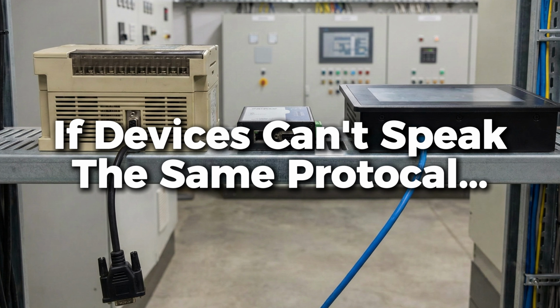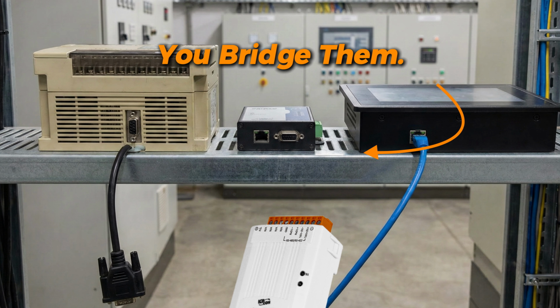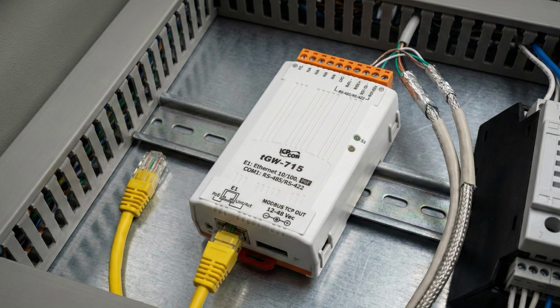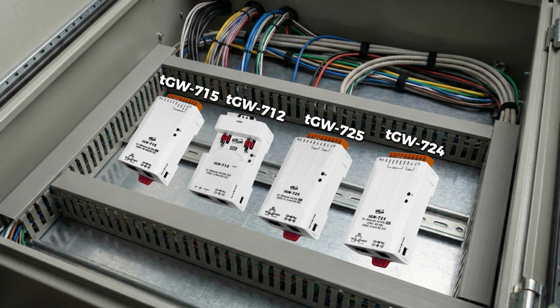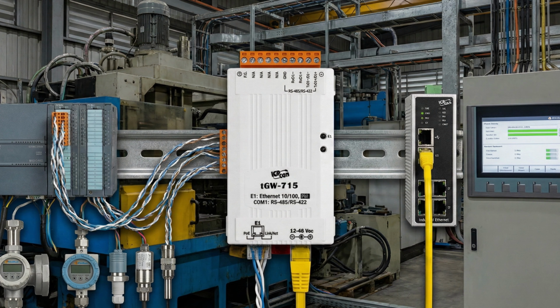So what do you do when your devices can't speak the same protocol? Well, you bridge them. This is where Modbus gateways come in. A gateway takes Modbus RTU on one side and converts it into Modbus TCP on the other, so everything in the system can communicate as if it were speaking the same language. And the TGW series gateways are perfect for this. They sit right between your serial devices and your Ethernet network, quietly translating everything in real time without needing to reprogram or replace any hardware. It's one of the easiest and most cost-effective ways to modernize an existing system.